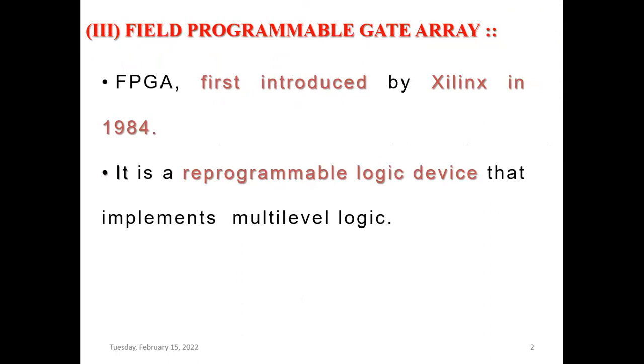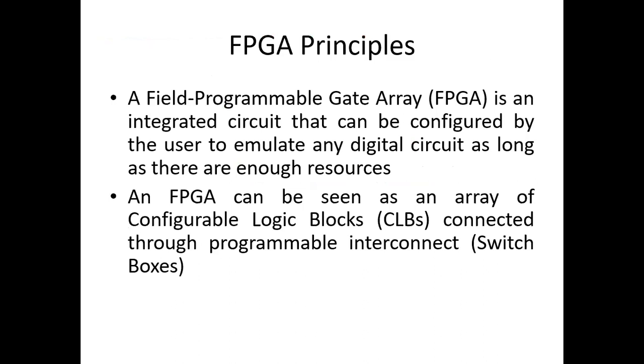In the case of the CPLD or SPLD, the basic device doesn't have multi-level logic, but the FPGA has the facility of multi-level logic. What is the advantage of that? If we are using multi-level logic, then we can implement a large circuit in FPGA.